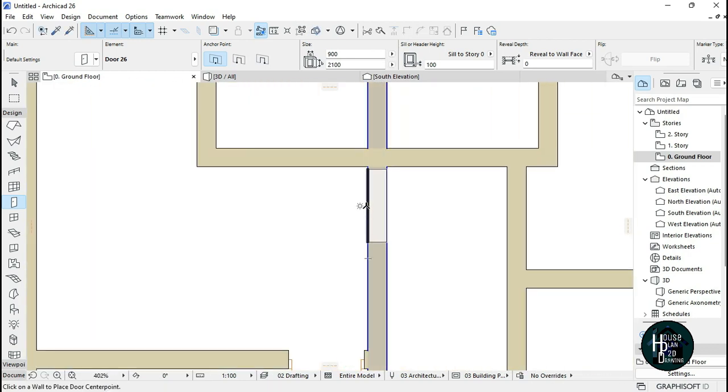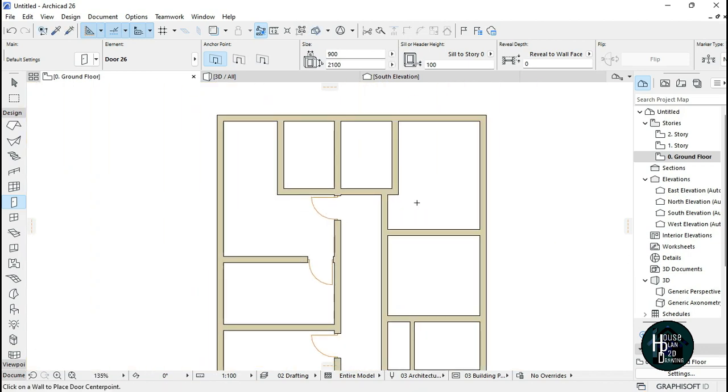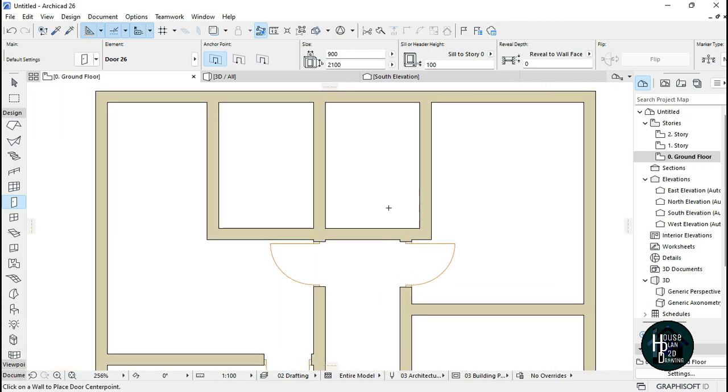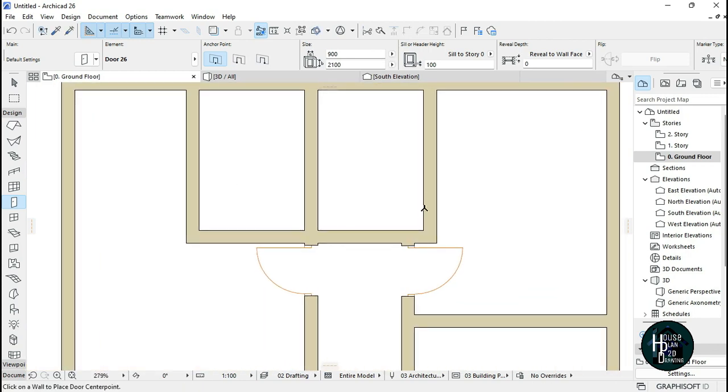Remember, all you have to do is click, move the door here. I want the door to open here, then click. So you're clicking twice. So also move your cursor here, click, then click. Now for the door, these are the toilets. I want the door to be opened by clicking this side and open this direction. Also for this side too. So clicking here, open this direction.